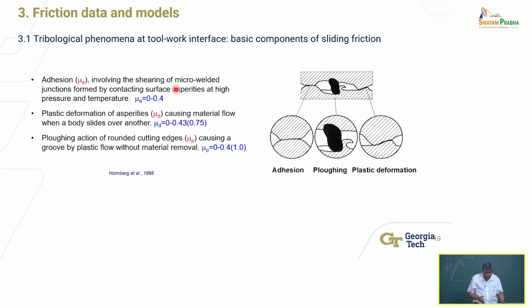So the apparent friction coefficient can be as high. What is friction coefficient? Tangential force divided by the normal force, right? If you were to compute that quantity, in this case, for machining, you'll get values much greater than 1.